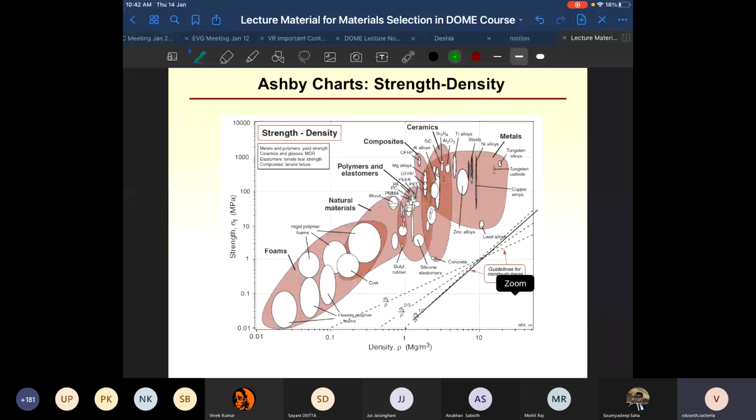All right. Next, let us move on to this strength versus density thing. We'll just talk only a little bit over here. Once again, we can do this exercise of what is the lowest density we have already identified. That is about 25 kg per meter cubed. The lowest strength: if you look here, how much is this? So this is 0.1 MPa, or 100 kilopascals, 10 kilopascals, 20, 30. So this is about 30 kilopascals.